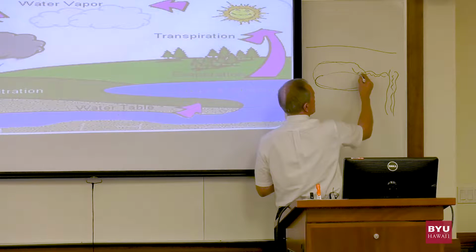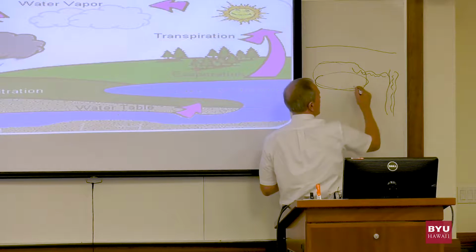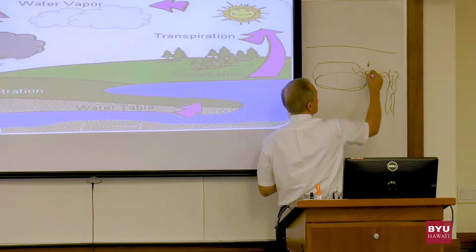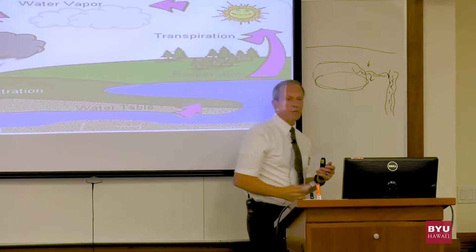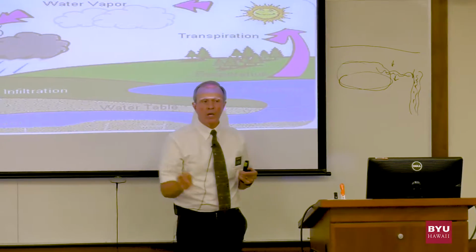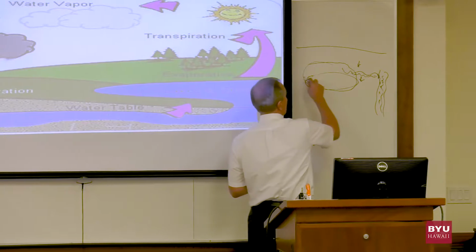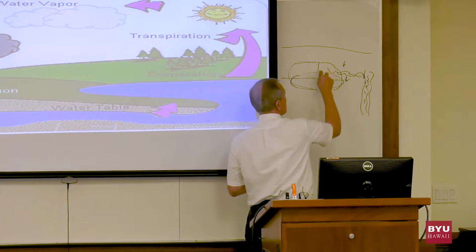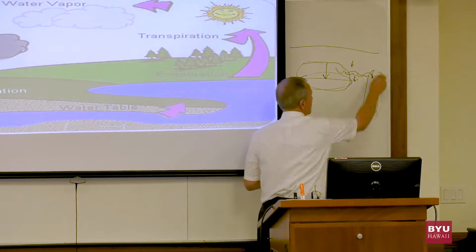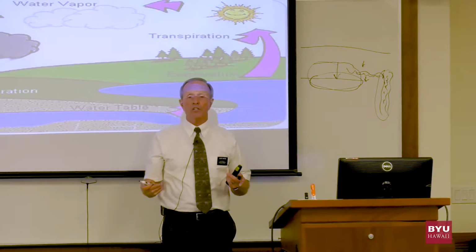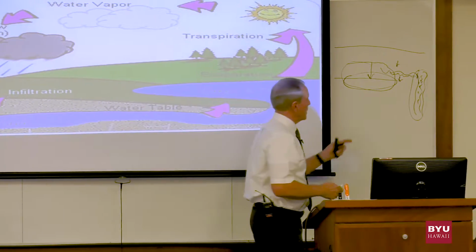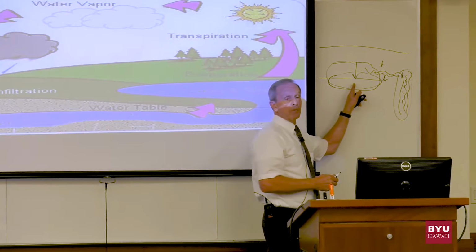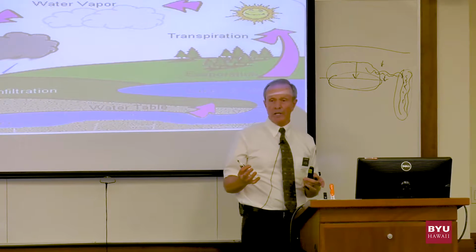If there's a little conduit, this water, here's your land surface, this water then is stored here. Well, there's enough pressure, and this is a low enough point, this water begins to flow. Hits an open channel, and all of a sudden you have this little stream that you didn't have before. Now, if you pump this too much and you drop that water level because of pumping down to here, that stream will dry up. And so that artesian head that you used to have is no longer available to you because you've dried this source up through the pumping or drought, maybe it doesn't rain anymore.